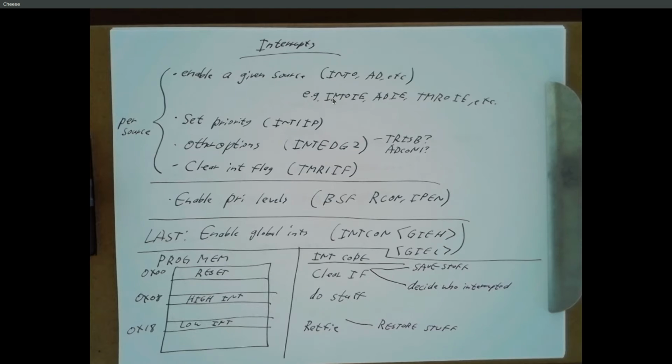But if you had a counter, or the classic case in the lab, you're using a delay routine, and you try to use that in your interrupt routine, well, that changes the value of those counts. And when you go back from the interrupt, your program is not in the same state it was. And so it takes 53 seconds for the LED to change again after that. All right, so save stuff. So that's a general prescription for interrupts.